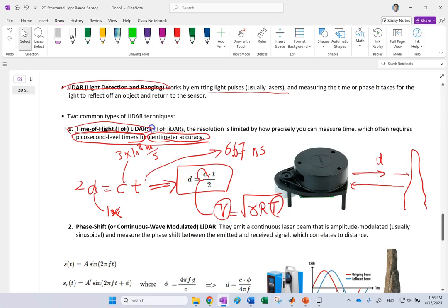So the thing about acoustic systems is, first of all, their range is much more limited than lasers. Second of all, they depend on the temperature. But the good thing about them is that if it's rainy or foggy, acoustic systems can do a little better than the laser, because the laser cannot bounce back properly, especially if there are visual issues like, as I said, fog or rain.